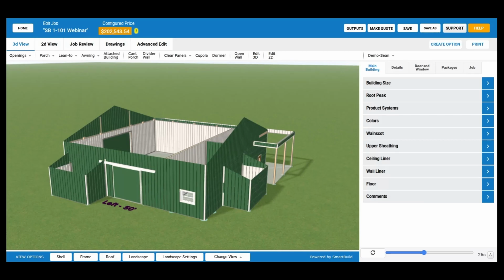So in addition to the inputs in the span table, if you think of a span table as, when I select auto for my eave post, for instance, that means Mr. Program, you figure out what posts I'm going to use by looking them up in this table. And this table needs to know what the building width is, what the wall height is, and what the loading is from the job tab.